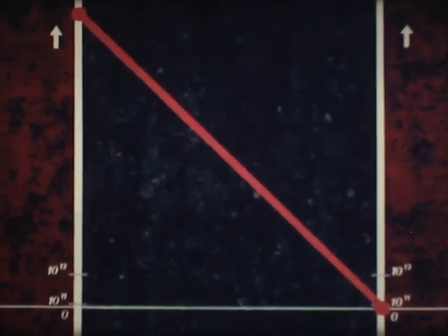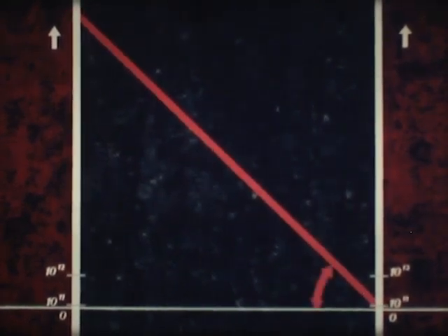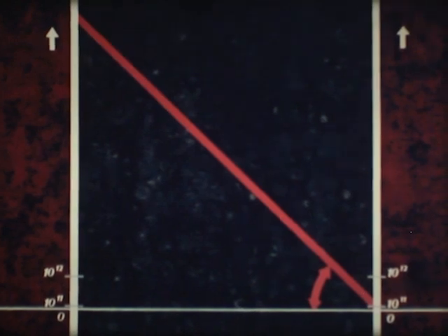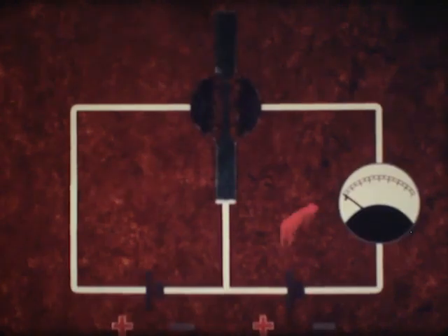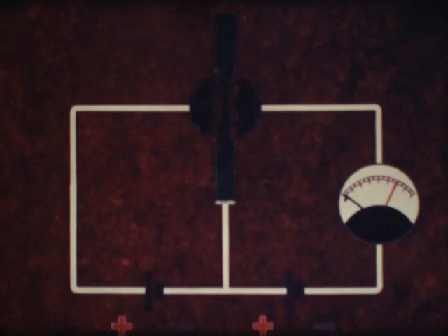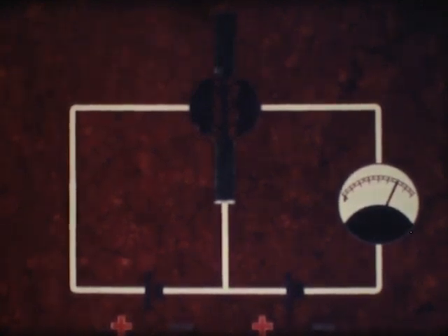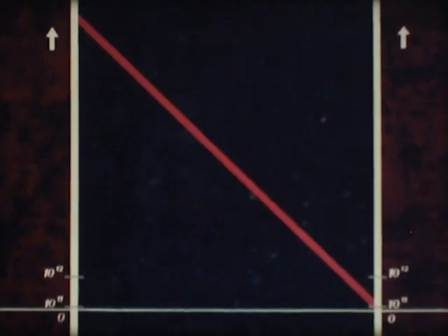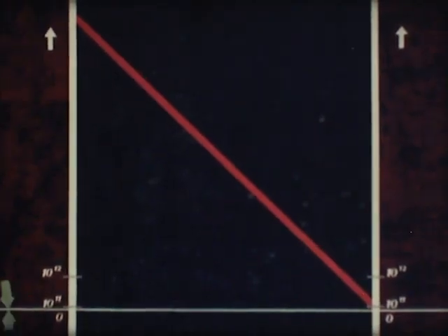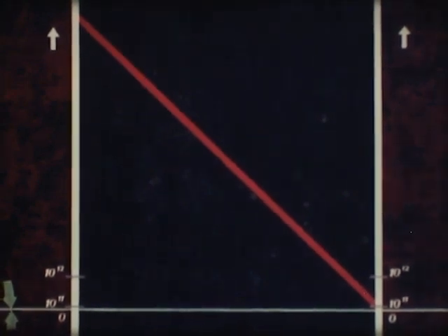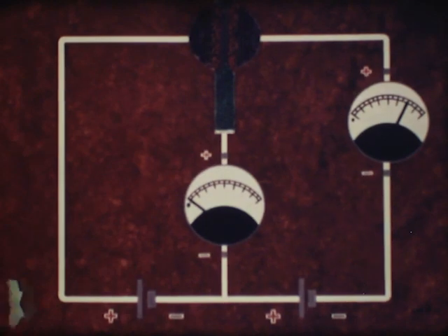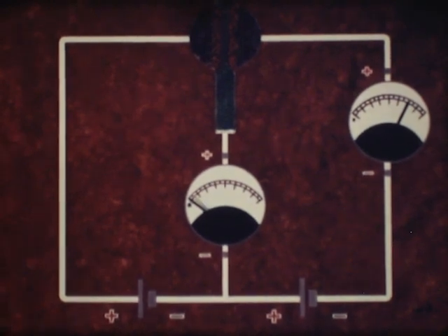If we now study the concentration graphs, we will see that the angle formed by the hole concentration curve with the horizontal axis is large. This means that an appreciable collector current is flowing. On the other hand, the angle formed by the electron concentration curve in the emitter is small, and therefore the base current, which may be expected, is also small.